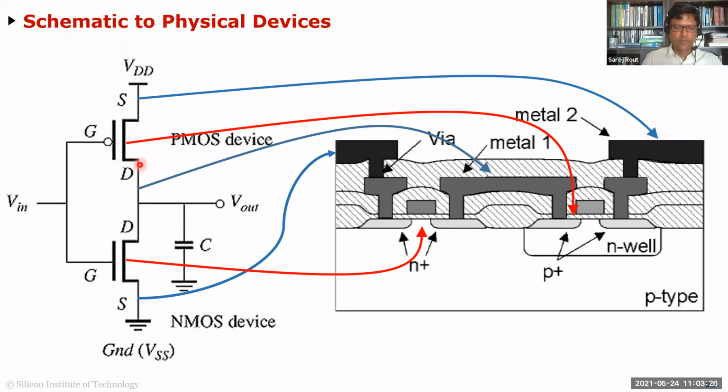So essentially what happens is you draw this and you simulate it in your simulator, your SPICE simulator. So for example, here it's an inverter. You have a PMOS, you have an NMOS and some parasitic caps here, or a real cap here, and you simulate this. But this is an abstraction, right? It's just a mathematical model. This three-terminal device, you can draw it any way you can. Like for example, like I keep saying, you can put your face here, put three terminals, and if it's the same model, it will give you the same result.